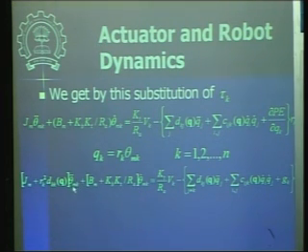Now here you observe that what we have done is we have taken the term corresponding to k equal to j out of this part of the robot dynamics equation, and then used this formula and brought this term over here. So you see this rk square into dkk of q is an additional term to the inertia of the motor.